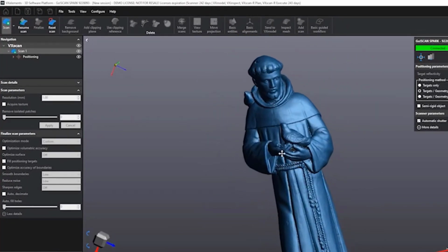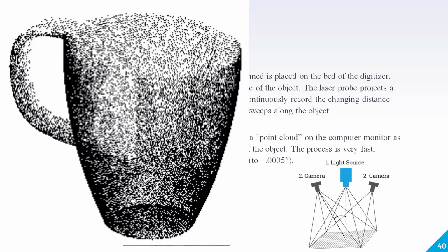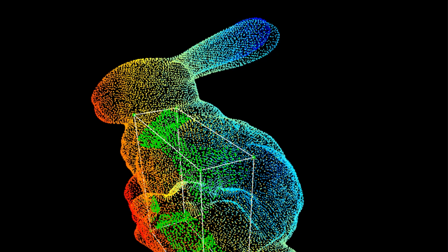So in 3D scanning, as I told you, it is very precise and you can scan up to 750,000 points per second. You will see lots of points, dotted lines. Directly from 3D scanning you will not see a 3D model, but you will see various point clouds, and by joining those point clouds you can create your model, which becomes your step 3.